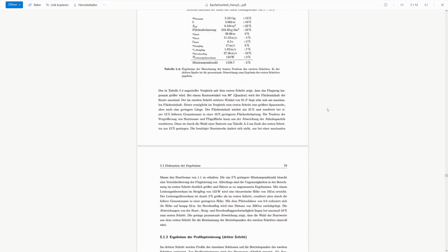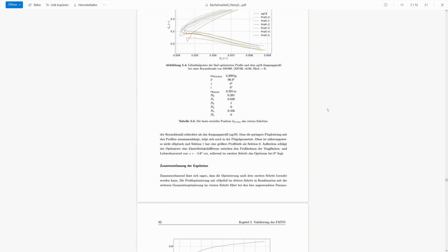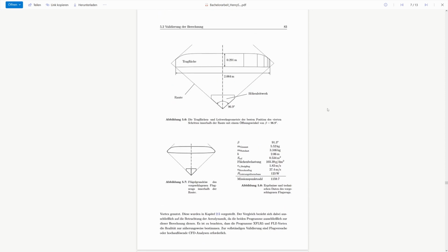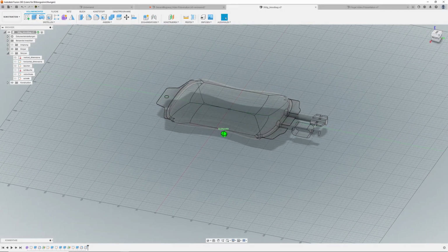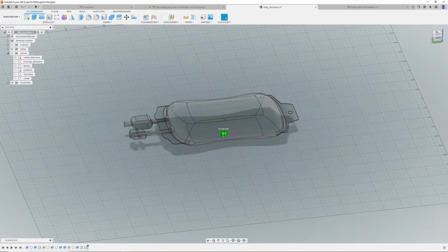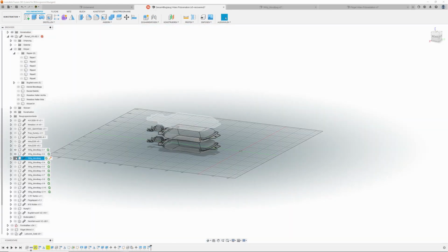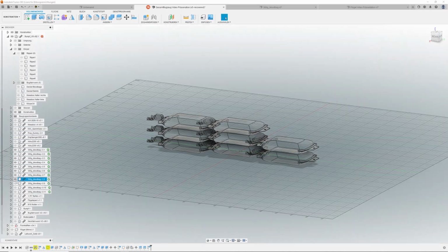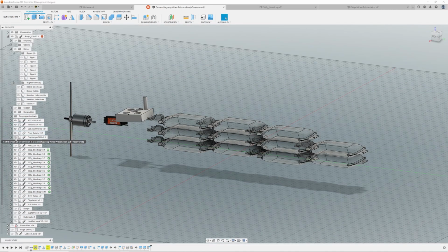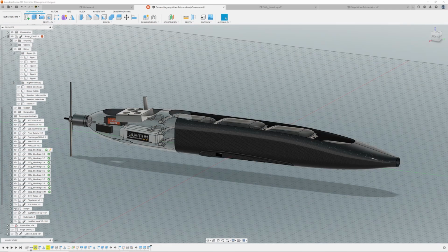After the last step of optimization, we had a basic aircraft design, as well as predictions for data like the maximum payload capacity, takeoff speed, and others. From this, we had to design a suitable fuselage, and to determine its size, we modeled the blood bags that would be used in the competition and arranged them in different ways until we found a good configuration. To this, we added the major electronic components and modeled a fuselage that could accommodate all of those.